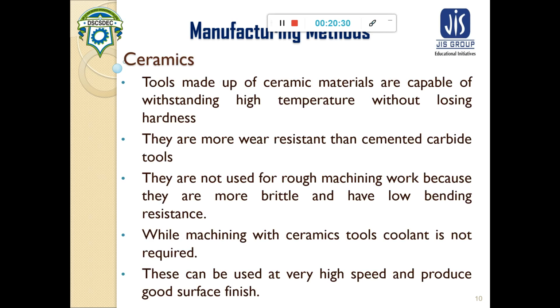Now in case of ceramic, the tools are made of ceramic material that is capable of withstanding high temperature without losing hardness. They are more wear resistant than cemented carbide tools. They are not used for rough machining work because they are more brittle and have low bending resistance.